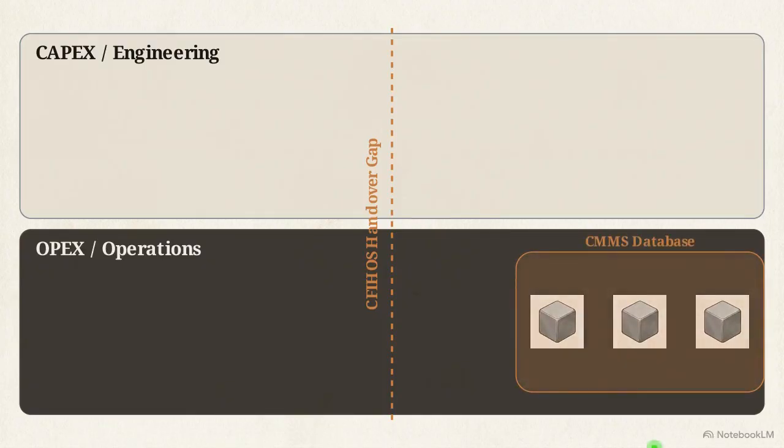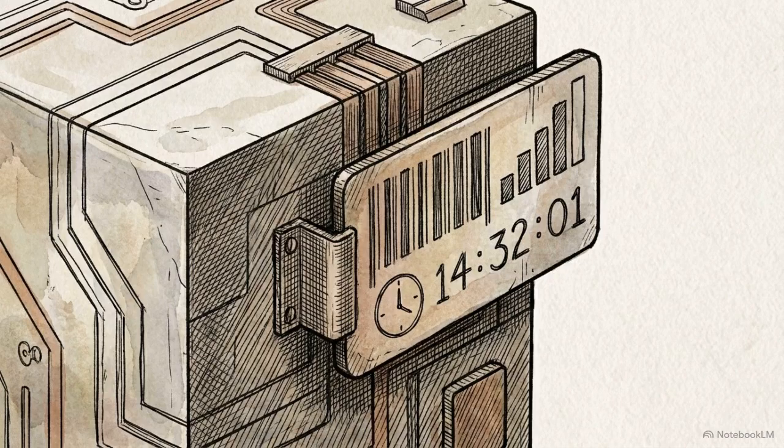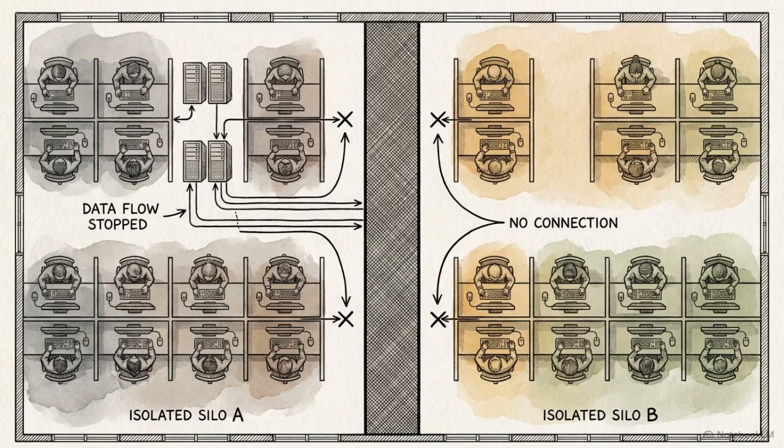Alongside static project files, a real-time stream enters the database, carrying operational technology sensor data. The OPC UA standard ensures this real-time OT data carries essential metadata context. It attaches the source device, an exact timestamp, and signal quality to every raw number. Interoperability standards prevent multi-million-dollar asset data from dying in isolated functional silos.